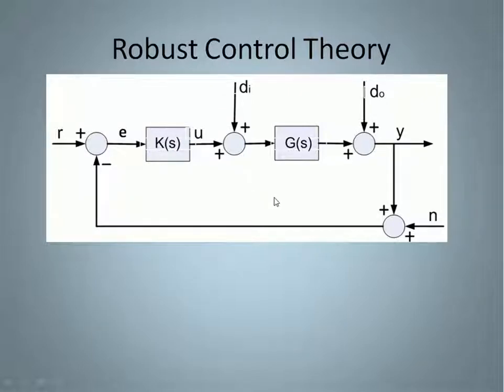I haven't mentioned yet a very important limitation in all control systems. The knowledge of the plant, G(s), is limited, and sometimes its mathematical model is an extreme simplification of a complex real physical system. Moreover, wear and tear change the plant's initial characteristics.